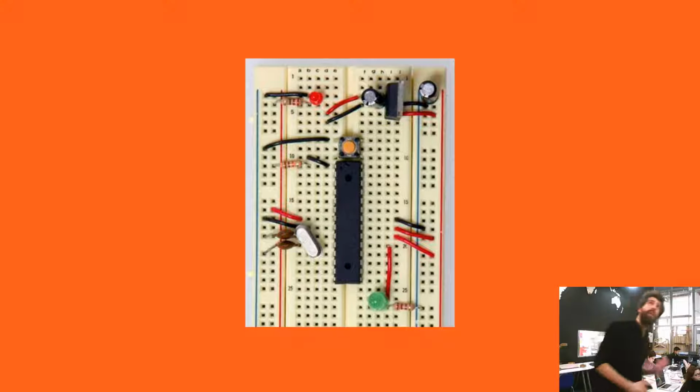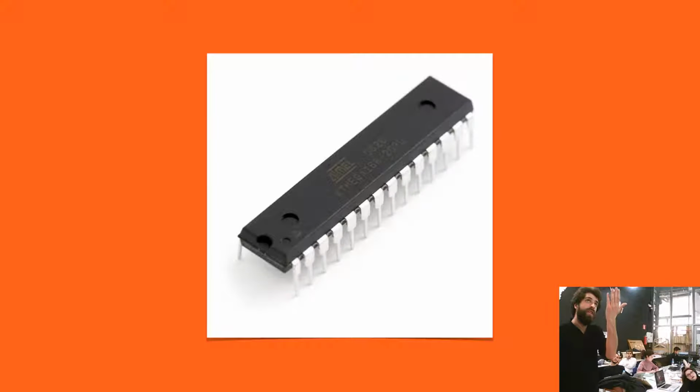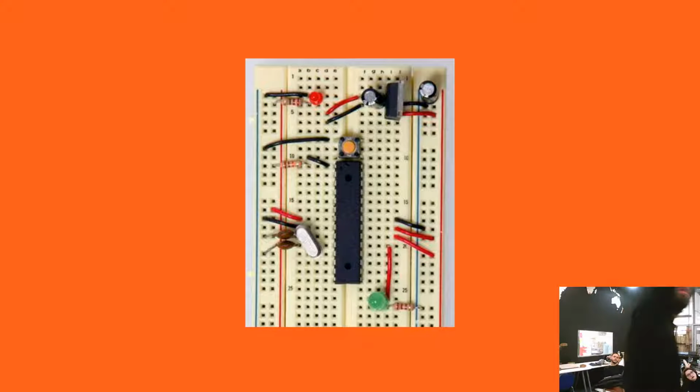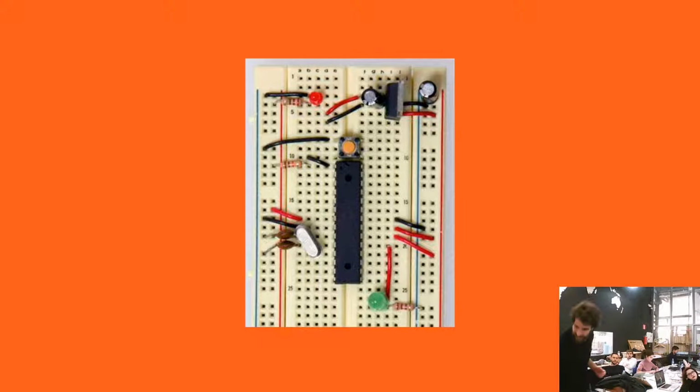So at the end, the important thing is to think that what this does is based on this, and you can replicate an Arduino like this. You just need the processor and a way to provide power to the processor. That's a voltage regulator, which just puts 5 volts to the processor. You will need a clock to count the time, because the processor doesn't include a clock, and you need an LED if you want to see that it's working. That's not compulsory. So that's the idea.